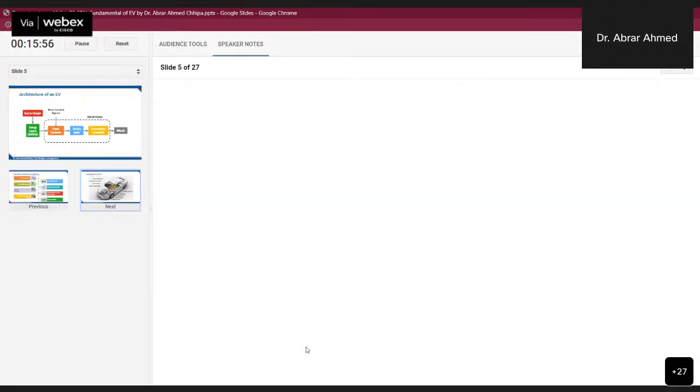These are all inputs from the user to the drive control signals, and they decide the power converter operations. The main part driving this complete system is the energy source, which is basically a battery bank. Most of the major cost of the EV is in the energy source, that is the battery pack and the charger. The charger can be onboard, meaning it is already installed in the vehicle, or you can have a separate dedicated charger for your EV.